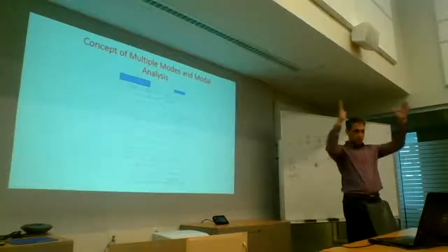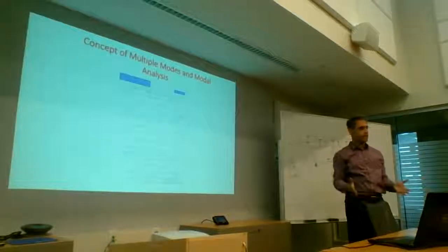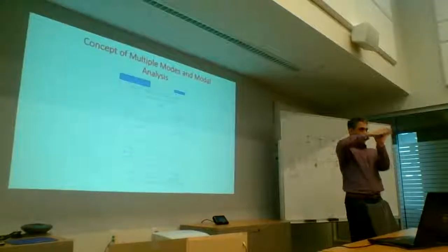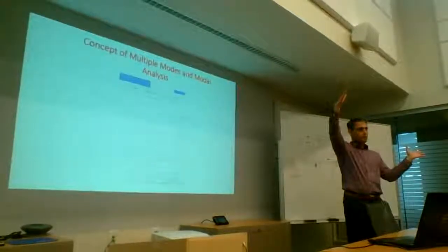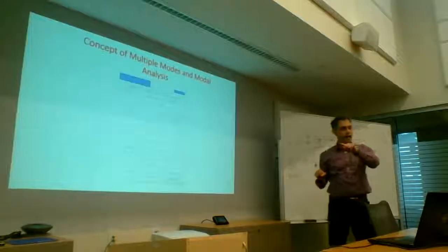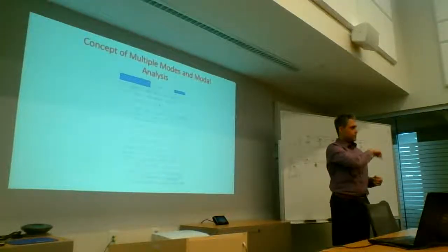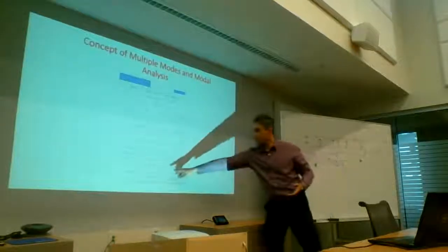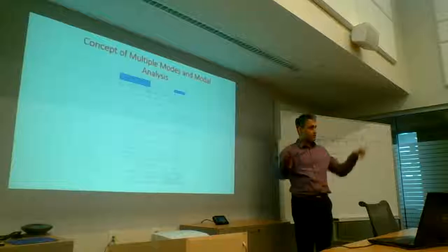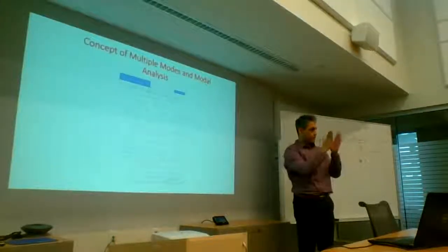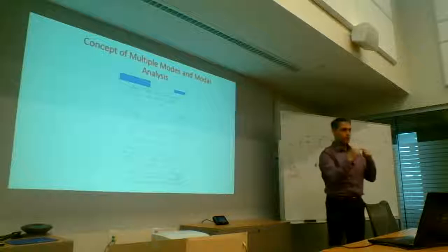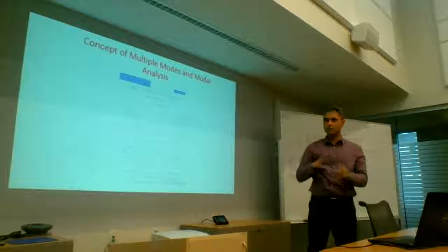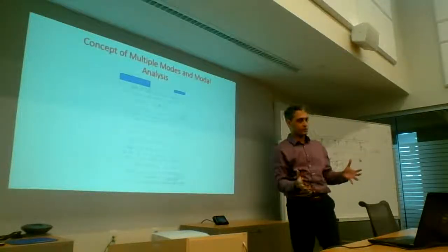That's not the original. The original is a large matrix, right? Because we have a multiple degree of freedom system. So this will be a diagonal matrix of K values. Every off-diagonal term is going to be 0. And now that K is only applicable to that particular single degree of freedom system. And that's how each equation becomes different. This P is also, originally it was a matrix of loads. Now it decomposes into a vector where the P is only applicable to one mode. So as you go down the rows, everything is independent, it's just assembled in a matrix.